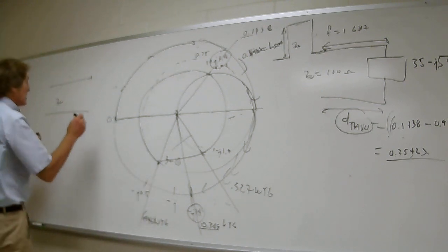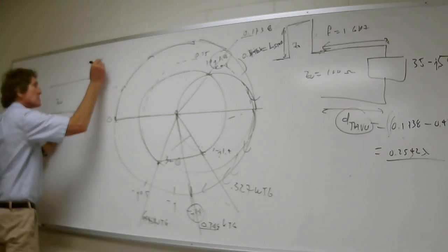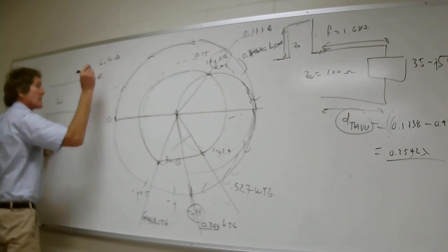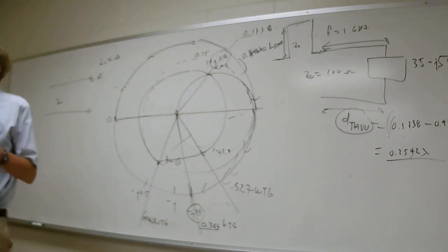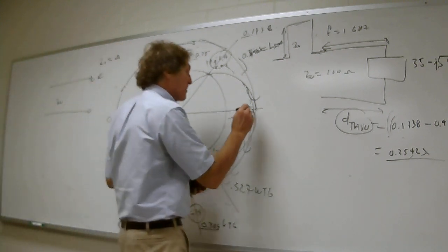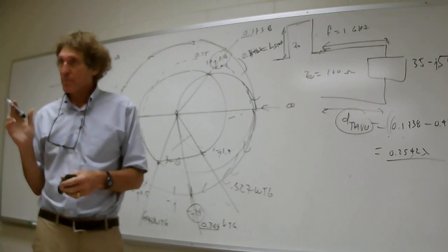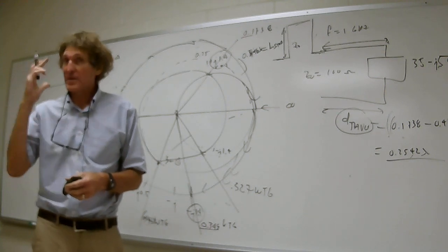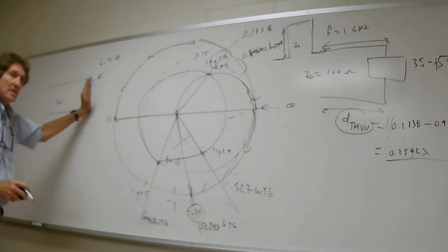This is an open. If it's an open circuit, what is the impedance? The open is infinite, correct? Normalize it, what is it? Infinite. Where is infinity in the impedance domain here? The very right, right here. This is infinity. Is everybody following the rationale? So on my Smith chart right here, that's the impedance.